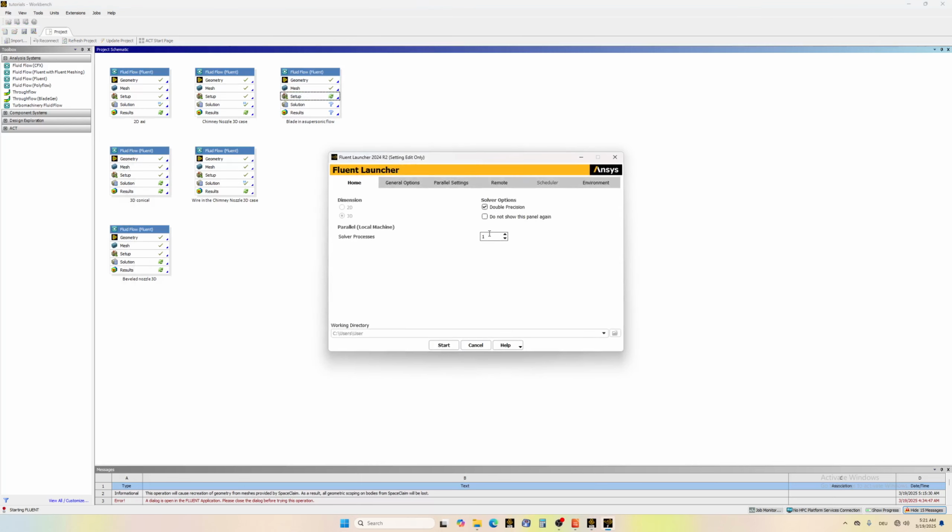Double precision. Here the number of parallel processes is 4 if you are using ANSYS Student, limited by the license otherwise. The next one is 128 if I remember well, and then it goes in steps of, I think, the next one is 5 multiplied by 128, so they are packages. Nevertheless, it doesn't matter. We choose double precision, we choose the number of parallel processes, start.